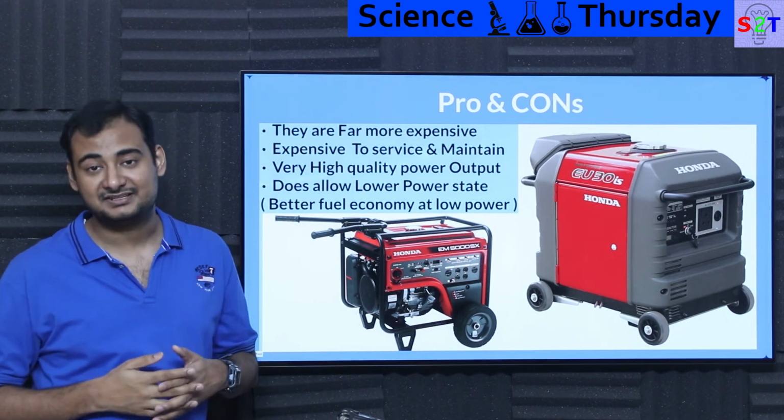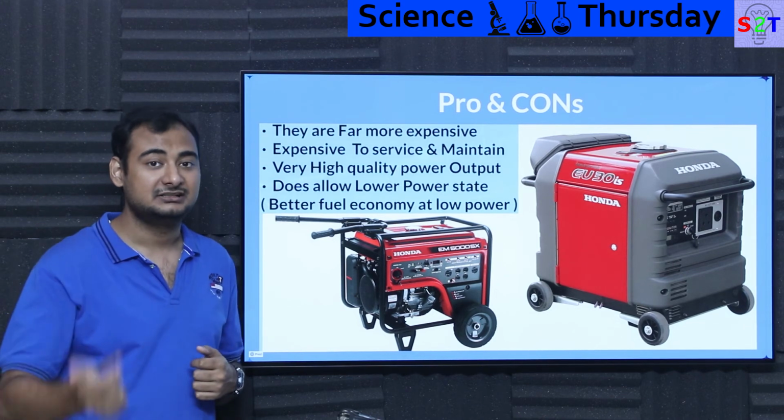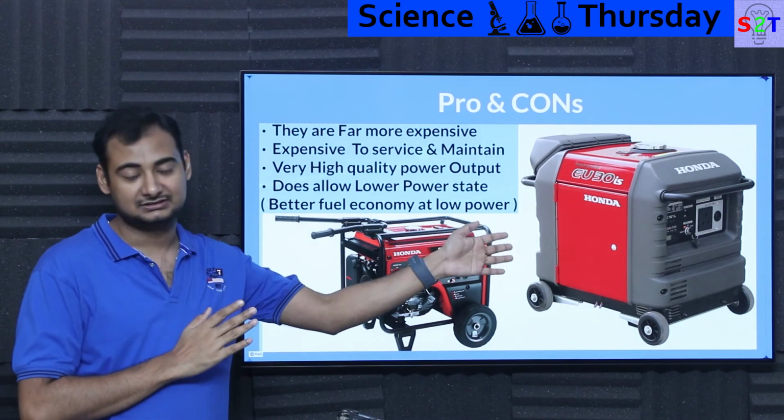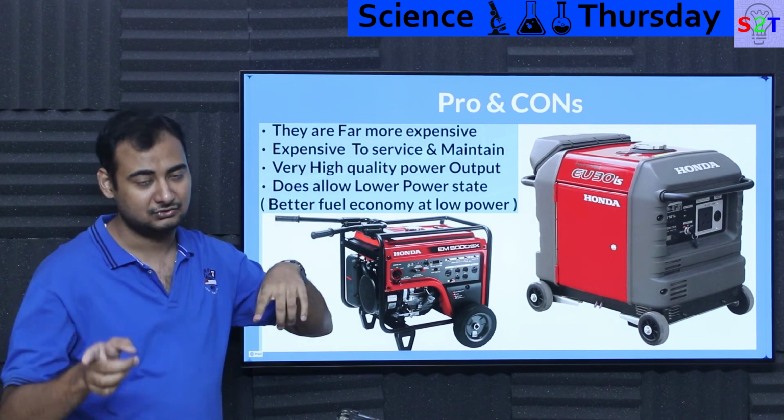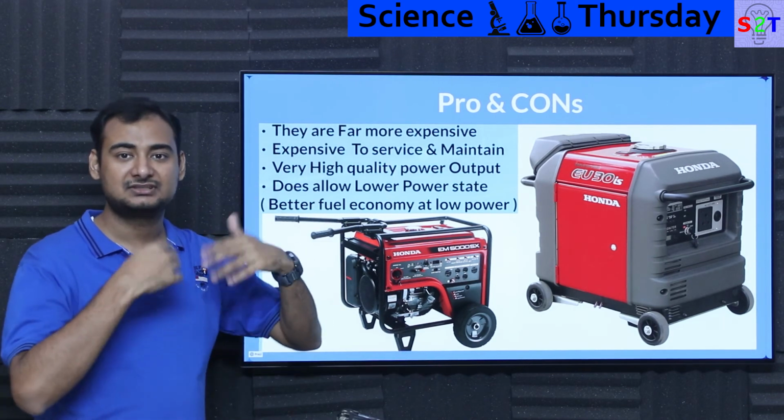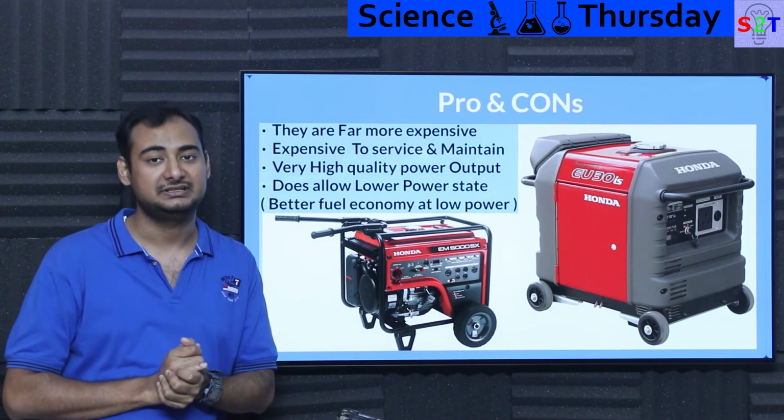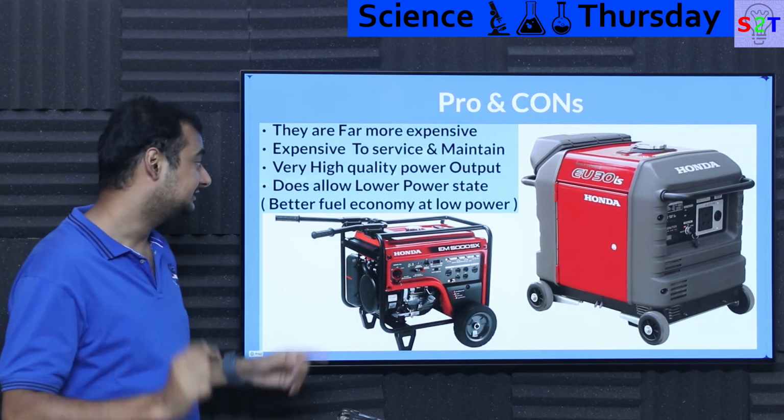And because there are inductors and capacitors, even if you directly started a big load, it will give the engine enough chance to detect it. It's like, hey, somebody is drawing a lot of power, and then it will open the fuel valves, RPM will pick up, tada, more electricity. So you get high quality power, and it allows a lower power state.